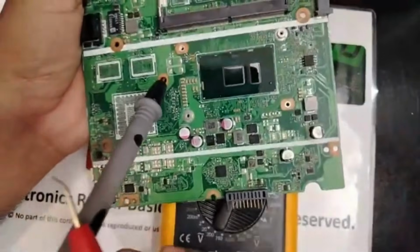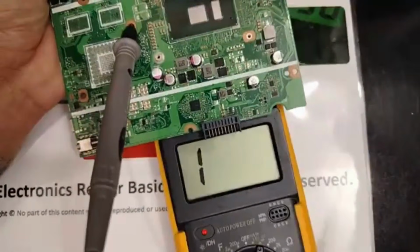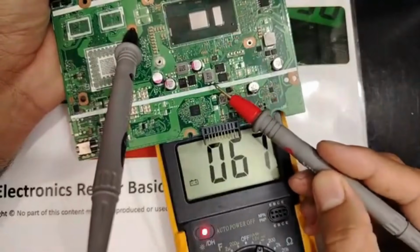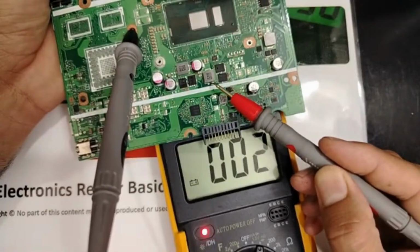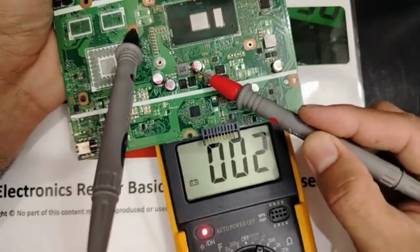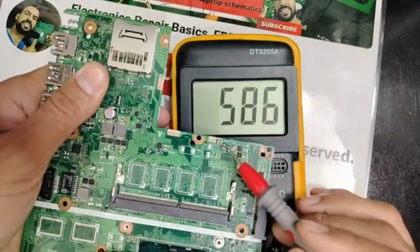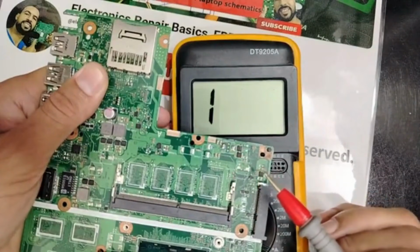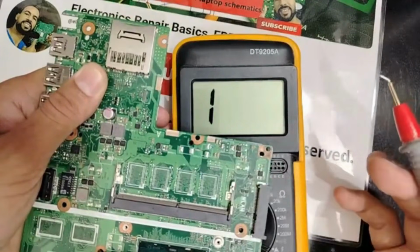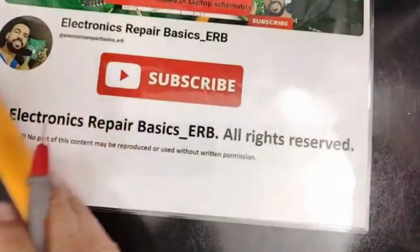If we check, for example, the processor, my friend, look, if I check the inductors next to the processor, we have 3. 3 is not a short. This one, we have 3, 2 is not a short. Means these ceramic capacitors are not shorted, my friend. I should not remove them. These capacitors are not shorted. Where is the schematic?